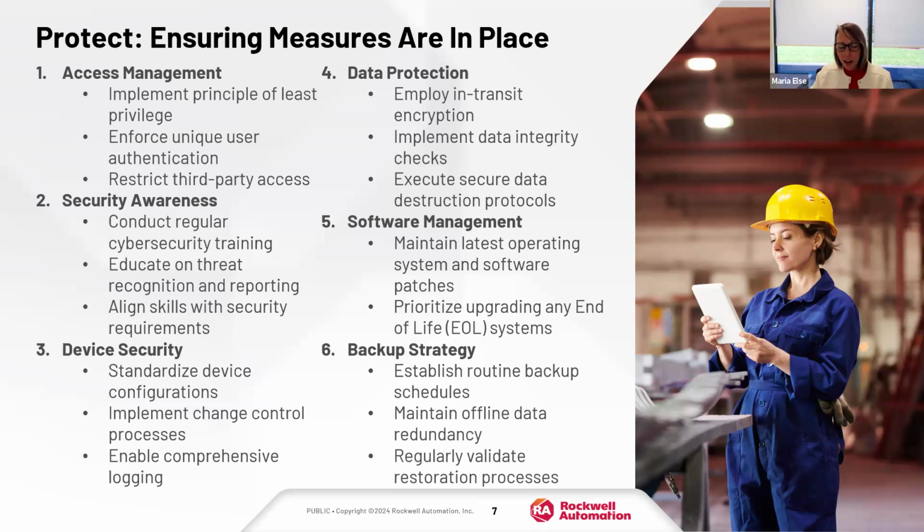From a software perspective, maintaining the latest operating system and system patches sounds very simple in your enterprise space. When it comes to industrial control systems, absolutely not. We've got to think about compatibility. Can I upgrade this OS? Is it going to break my application software? How do I manage all of this complexity in my space? And think about how we work with and manage end-of-life legacy systems, which is one of the biggest issues we see today.